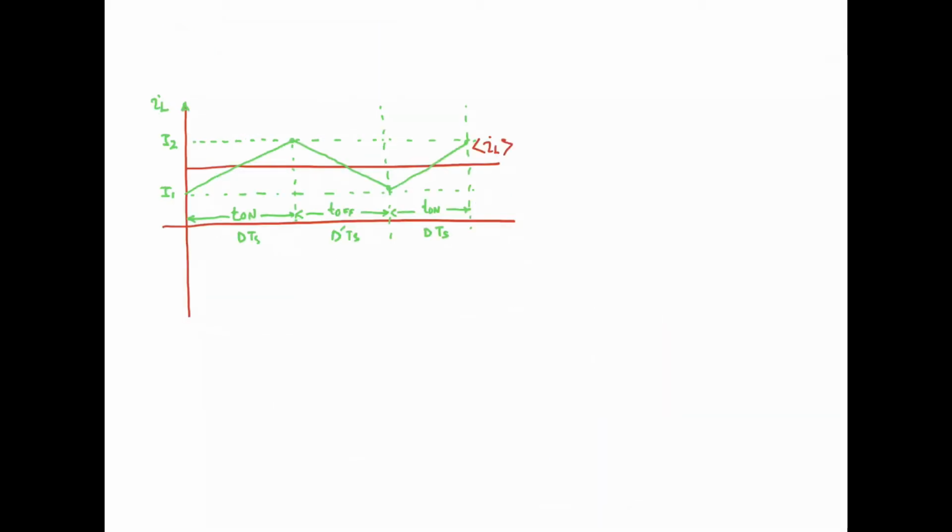So now if you decrease the inductance, this waveform will be changing like this. At one particular value of the inductance, the current waveform may be represented like this, just touching the 0 point over here by the end of the cycle.